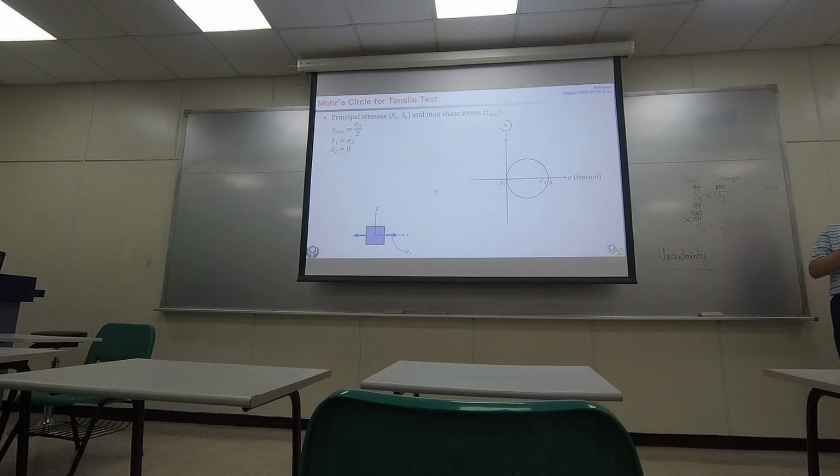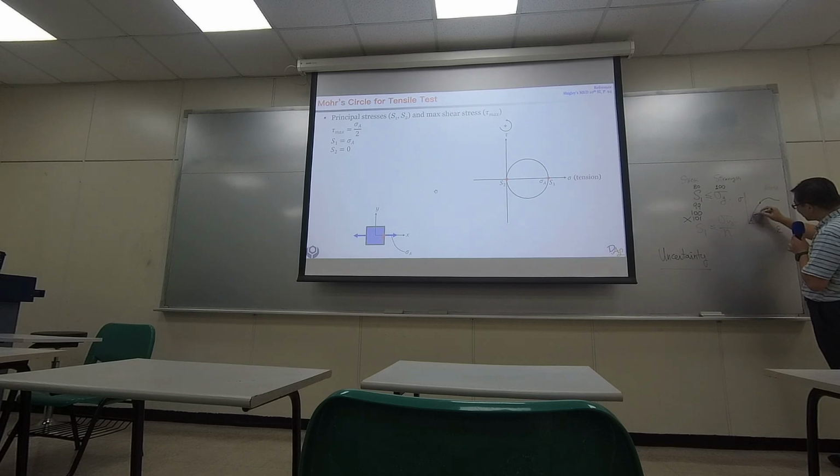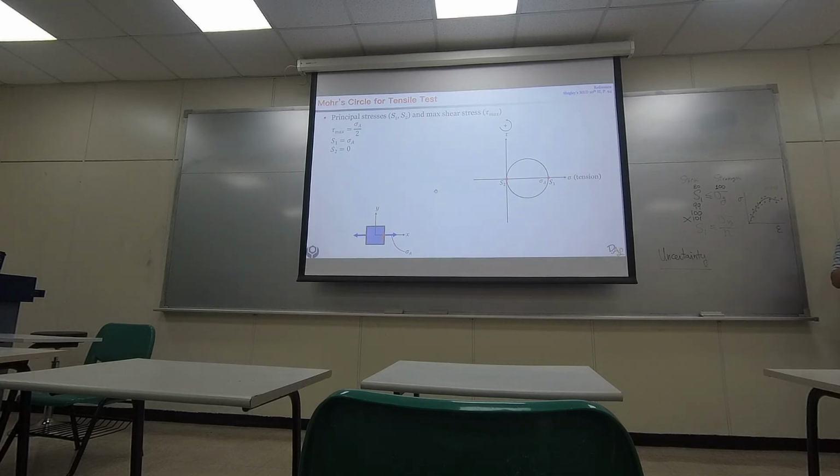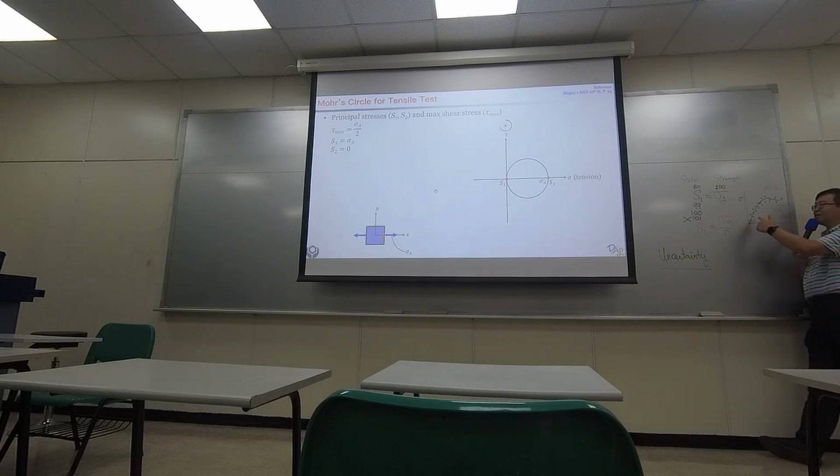If you are not sure, do your own experiments. Usually, if you check any textbook, when people show you the stress-strain relationship, they draw a very ideal curve like this. But what happens in reality? If you do real experiments 10,000 times, every time the result may not stay on the straight line. There are uncertain changes to the real situation.